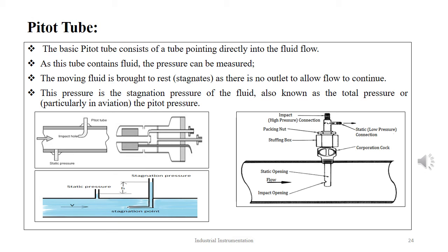The measurement of the total pressure, that is dynamic plus static, is done, and a second measurement is required for the static pressure. The difference between the two measurements gives a value for the dynamic pressure. The flow rate, like any other device, is calculated from the square root of the pressure. In calculating the flow rate from the pressure, the calculation is dependent on factors like tube design and location of the static tip. The pitot static probe incorporates the static holes in the tube system to eliminate this parameter.